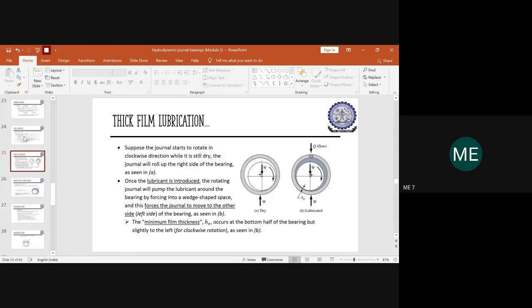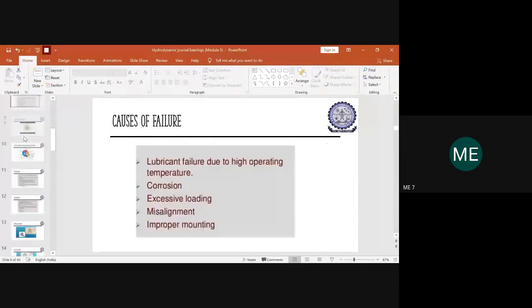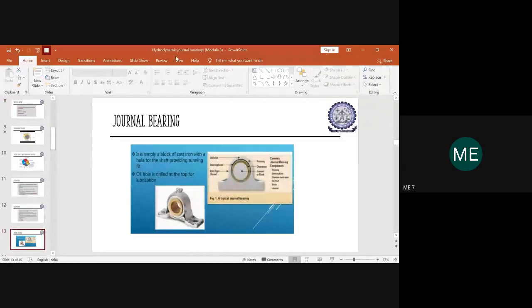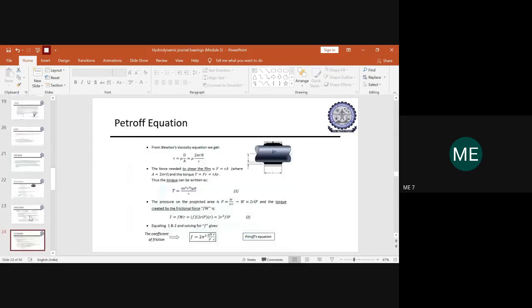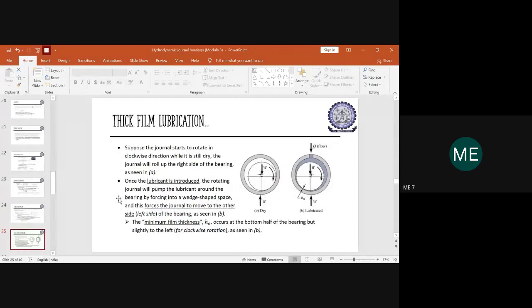So I have shown the sketch of exactly how a journal bearing looks. If we go back to the diagram, you have a casing with the shaft, and around that you have a bearing liner. In between there is a clearance through which the oil from the inlet passes, forming the required lubricant film. The shaft itself is termed our journal. We have also discussed the components associated with bearings. Now let us go with the nomenclature before proceeding.